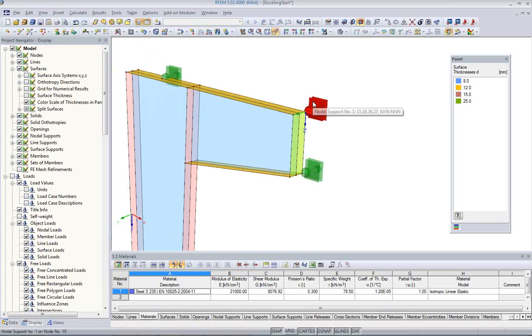And if I want to introduce a bending moment of about 360 kilonewton meters in the center of the column, I need approximately, because we have here 2 meters, approximately 180 kilonewton of force here in the end of the beam. Now if I want to do some kind of parametric analysis, I could calculate 180 kilonewtons divided by 0.6 meters, and I would get the value. But I have to do this each time I would change the force. I show you how we could do it a little bit more elegantly in the software.